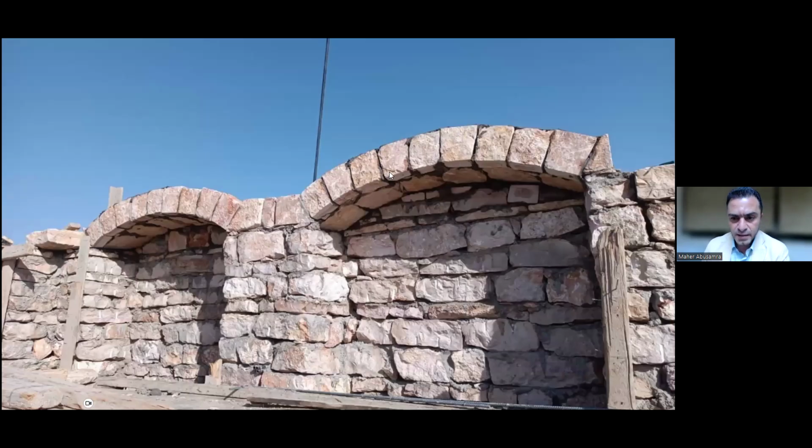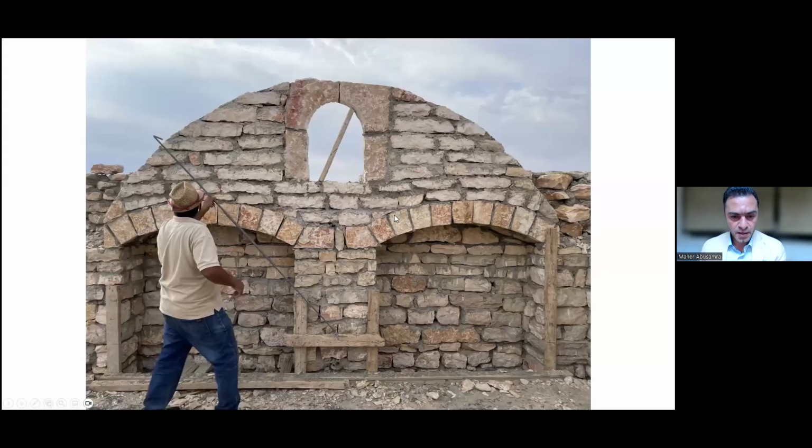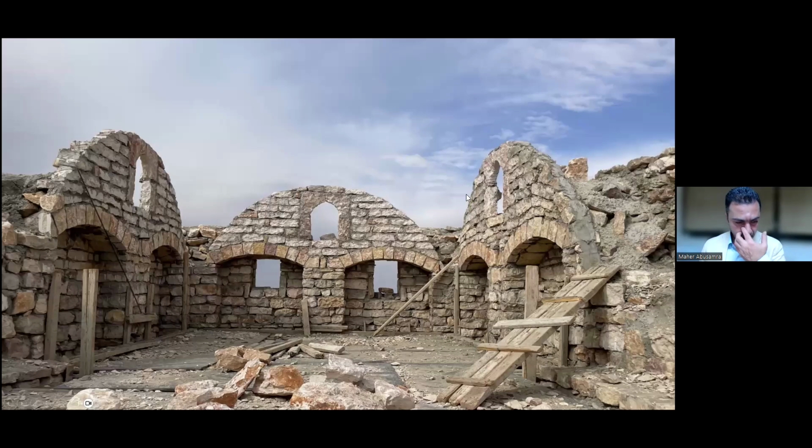Here, I add some pictures about the construction technique. I divided the wall into two segmental arches to minimize the span and also make the wall stronger. Then after those two segmental niches, I built the wall with a semicircle shape to construct the shallow dome or the sail vault. So here we have three, and the fourth one at the back.